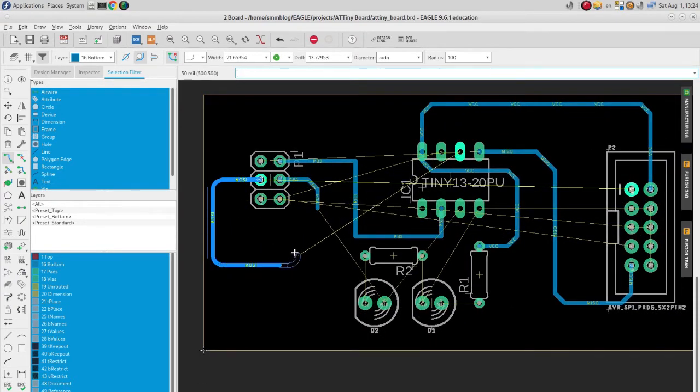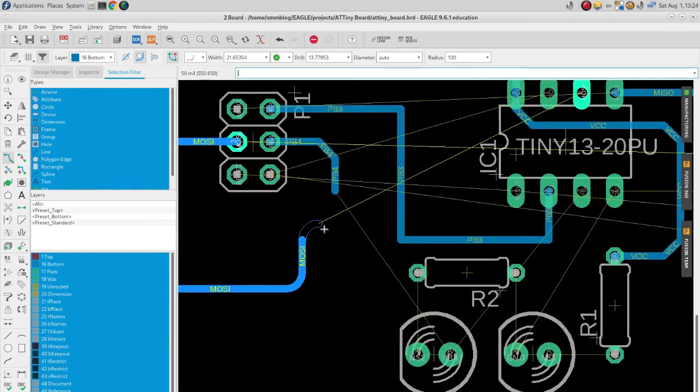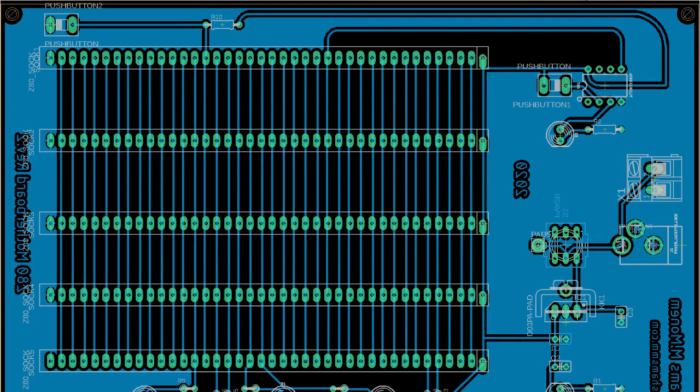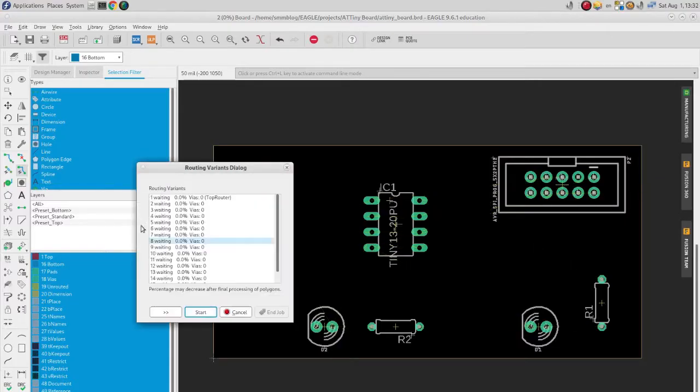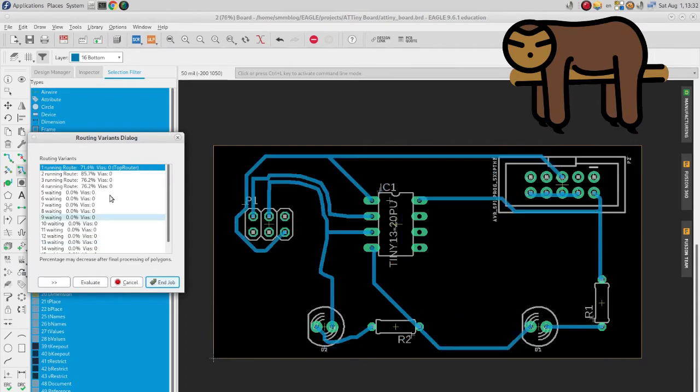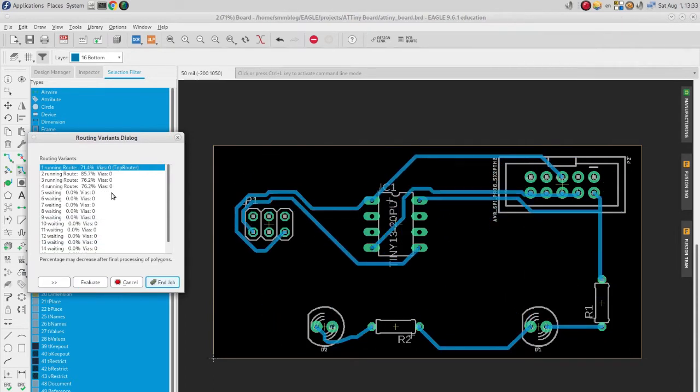You might also use what's called a ground plane, where all of the rest of the PCB is just a big ground plate, which also helps filter radio signals and maybe electromagnetic interference and stabilize things. But I will not do this in this circuit. Well, I will not lie, I'm actually lazy and I just leave the auto router to do it for me.